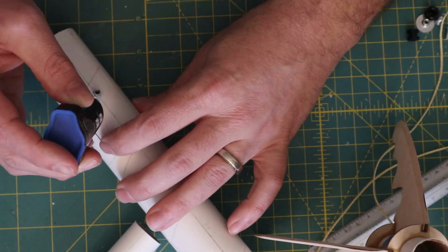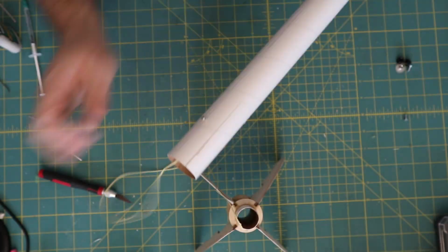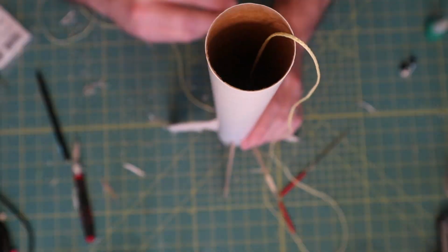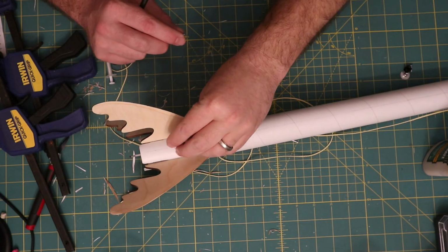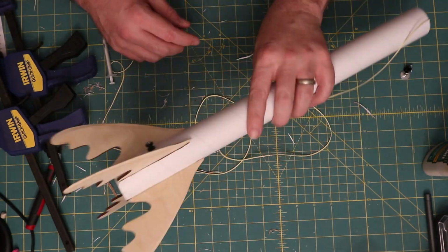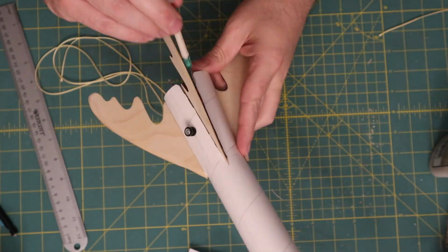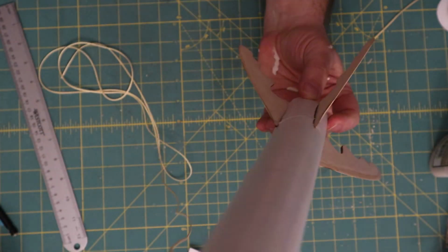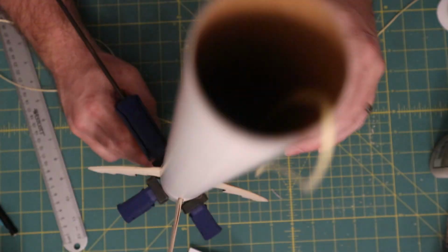Then we're going to measure off a few body lengths of shock cord and pass that through the body tube so that we can mount the fin can. That, of course, is going to involve more fillets of glue. So we're going to start on the top and do the transverse fillets on the inside of the airframe. Then we'll flip it over, do the bottom side of the top centering ring. Then we'll continue with the bottom centering ring. We'll clamp each of those in place and let them dry before moving on.